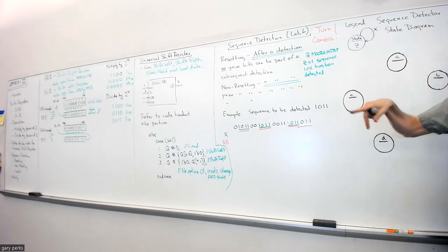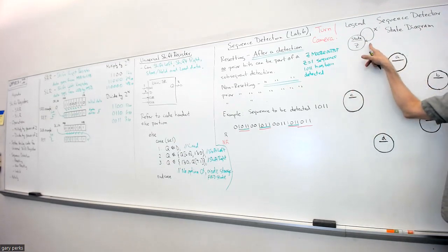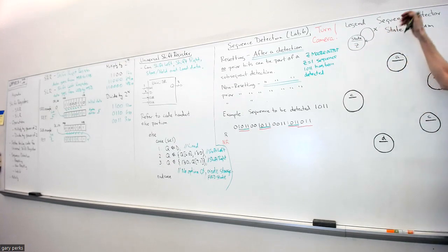Clock edge, right? Clock transition. That arrow represents a clock transition, and it's a conditional clock transition because there's something here. Remember, if it's unconditional, you won't see anything there. But this X, that's an external input. And that X represents a bit of our series of bits.